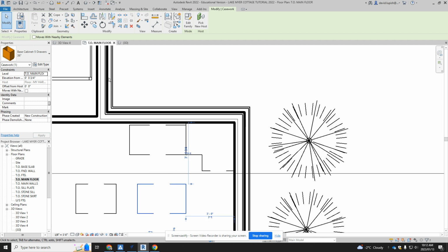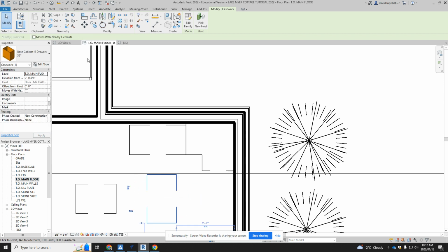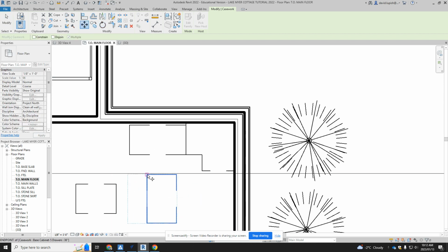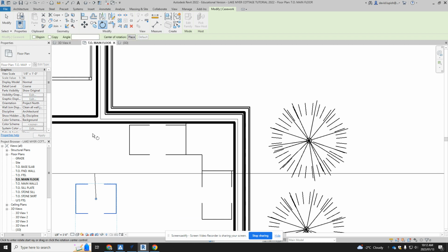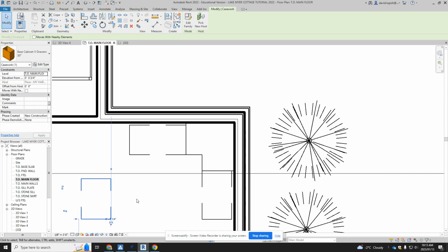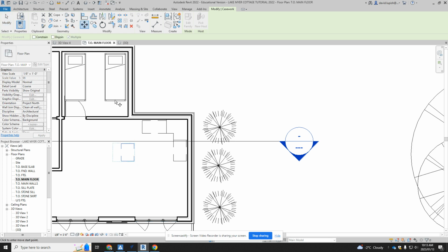This one here, what I'd have to do, I know that the drawers are on this side, so I'm going to use this rotate tool. And if I click straight up 90 degrees here, I can rotate this 90 degrees that way. And then I have the ability to move my cabinetry over here if I want. And I'll do the same with this. I'll do a rotate, making sure that rotate line's at 90 right now, and then I can do a 90-degree rotate on that. And again, move things around the way I want it.